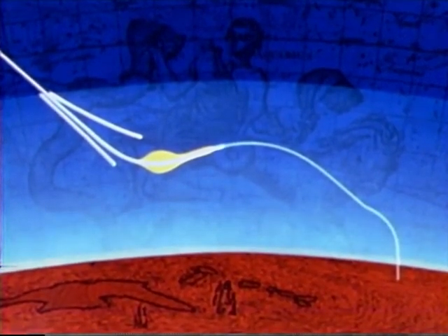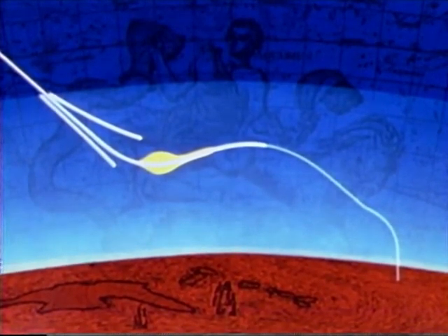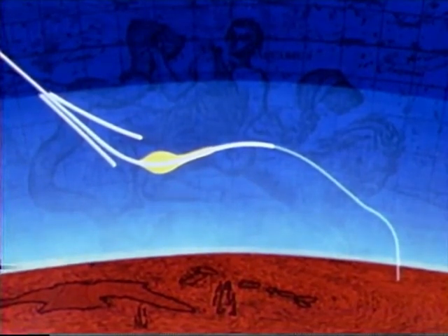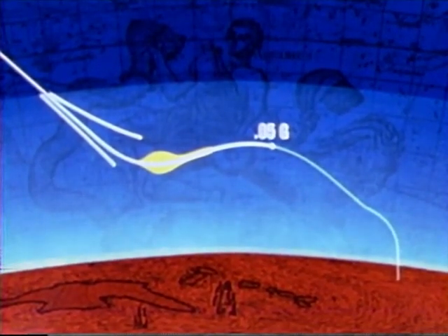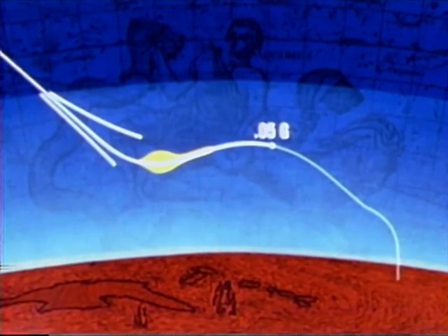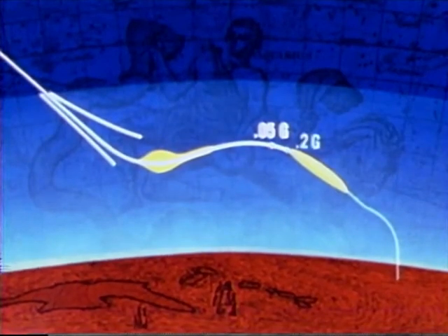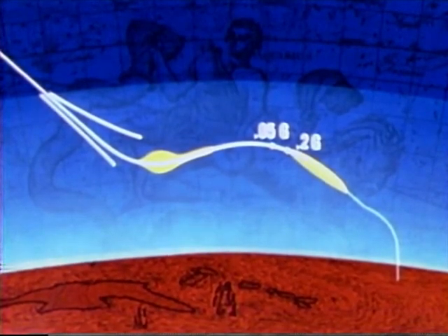During the skip, the crew will ride along and monitor the trajectory, but will have no control over it. However, the command module will be aligned to its trim position in preparation for the second entry. As in the first entry, aerodynamic stabilization begins at the 0.05 G mark. The spacecraft must be properly aligned by this point. The second control period, beginning at 0.2 Gs, will last a minute and a half.